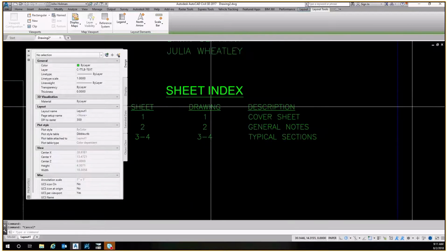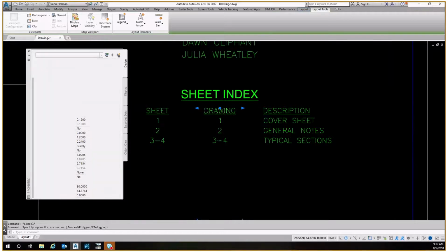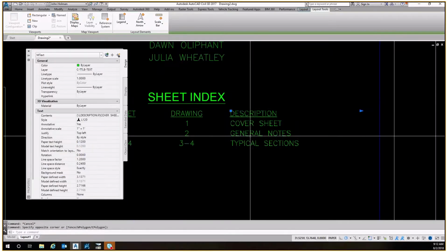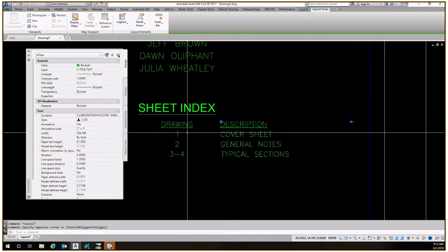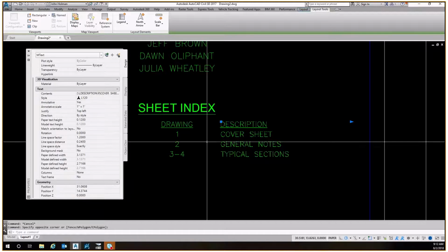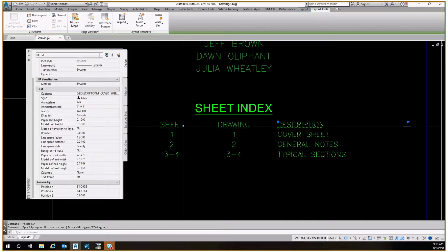And since the X position for here was 30 as we made it, and this is 28.5, that's a 1.5 inch difference. Let's go ahead and, oh, actually this is left aligned, so never mind. What I was going to do is not going to work. I was just going to set it, if it was center aligned, to make it 1.5 inches from the drawing, but we're just going to have to take a little guess to make it clean and look right. Let's see what this distance is.